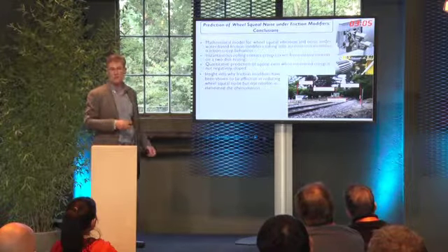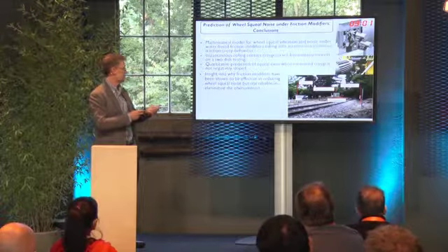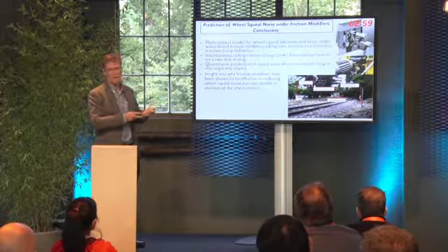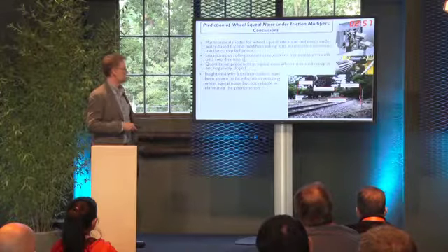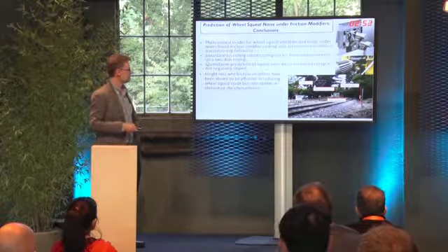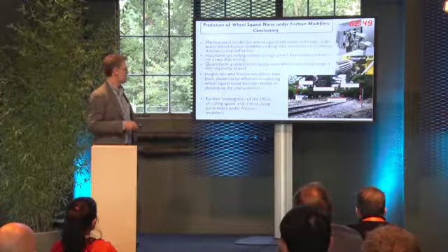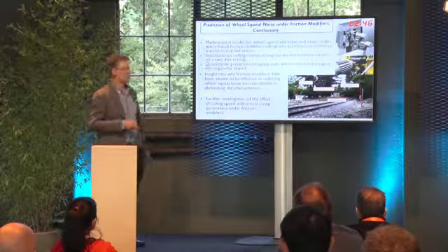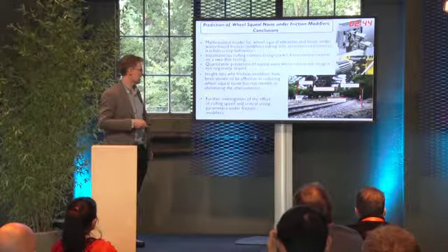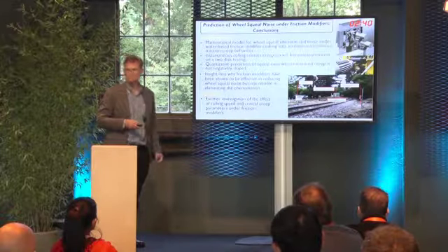This provides some insight into why friction modifiers have been shown to be effective in reducing squeal noise, but perhaps not reliable in eliminating the phenomena at all speeds. So in future, we'd like to do some further investigation of the effect of rolling speed and critical creep parameters under friction modifiers. Thank you.